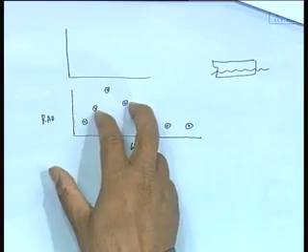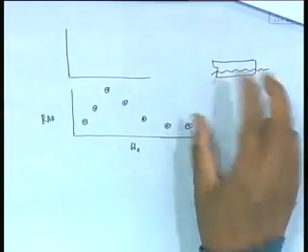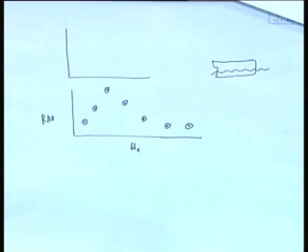Where it responds most, as we discussed, the inertial response and the static response, is where wavelengths are comparable to the ship length. You will always see that in your strength calculation. How much wavelength do you choose, the trochoidal wavelength? You have done the strength calculation, right? You have done the wave bending moment calculation, assuming a wave profile to be static, with L by 20 as the height. What was the length you have taken? Why not more length? Why not less length? Maximum effect happens when the wavelength is comparable to the ship length, so the maximum dynamics are involved around there. Actually, it is not strictly true though. The truth is that the maximum occurs at a little more than 1, about 1.05, 1.06 type, but never far from around 1. So you see lambda by L around 1, which means maybe 0.25 to say 4.